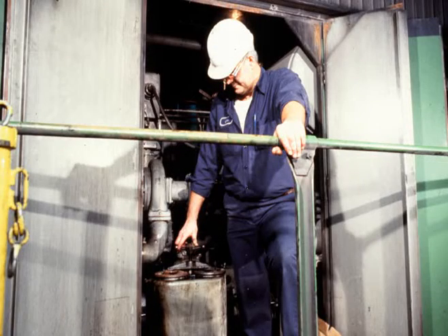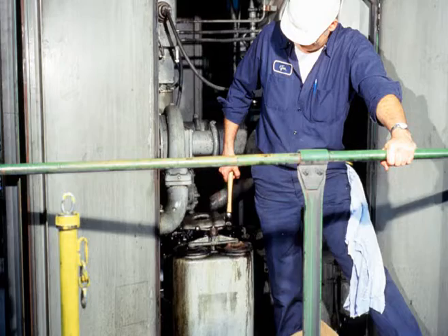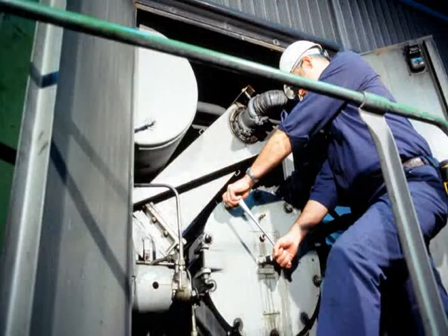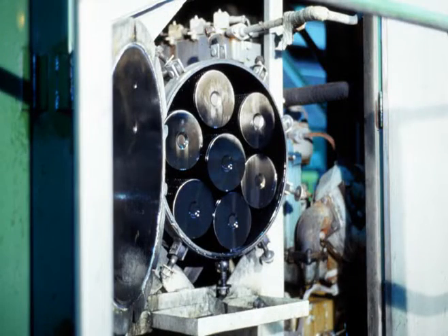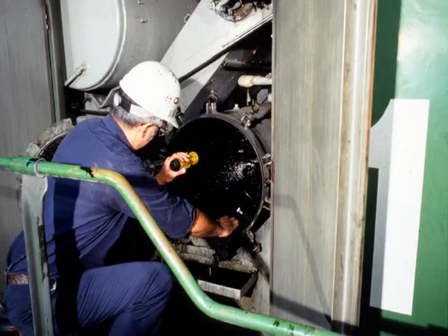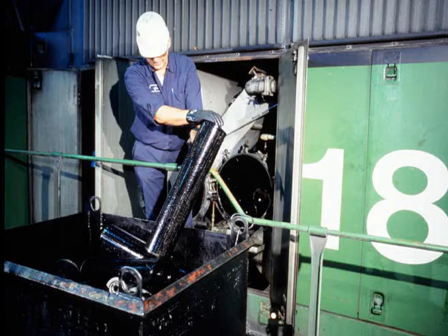Apply the star-shaped wheel. Tighten firmly. Next, loosen the nuts on the filter housing cover plate. Carefully open the cover and remove the filter elements. Examine the housing and the elements for signs of metal particles that may be in the oil system.